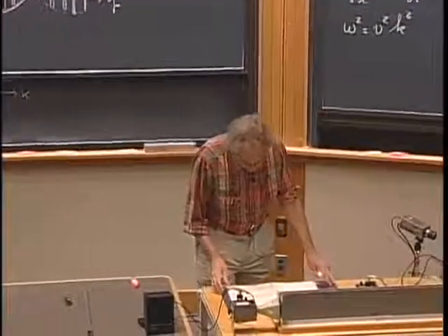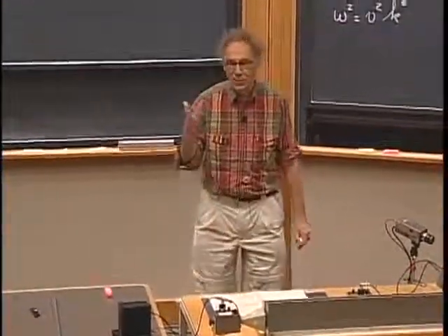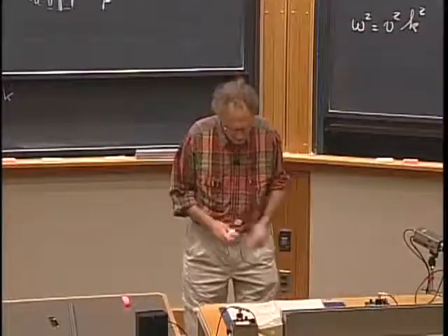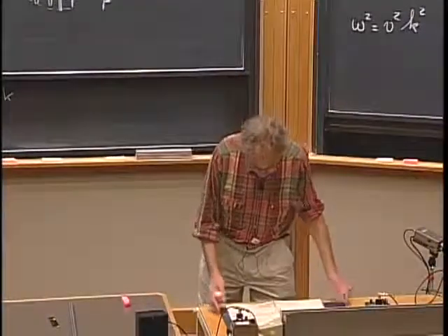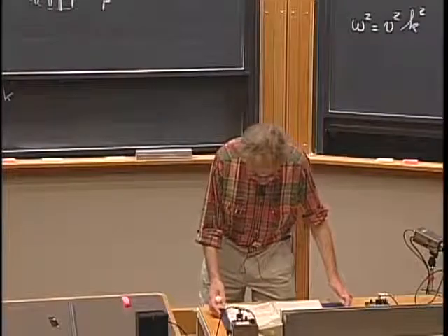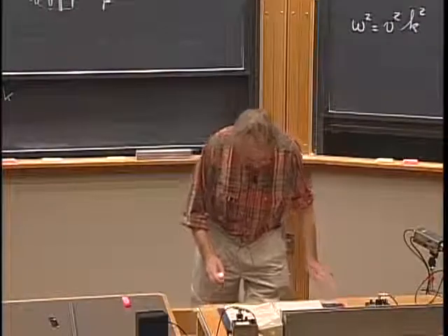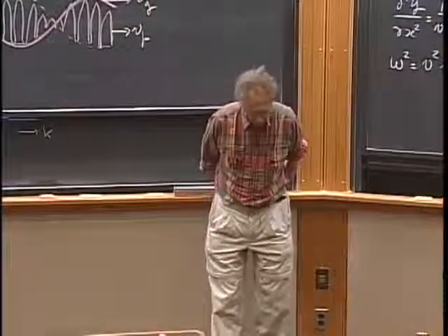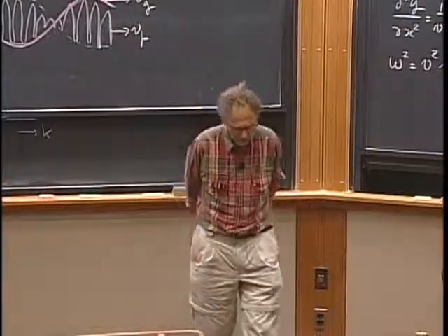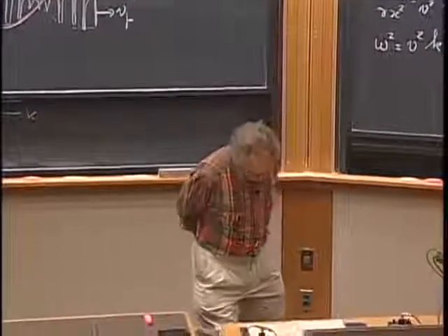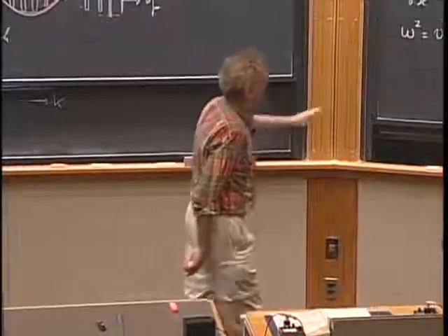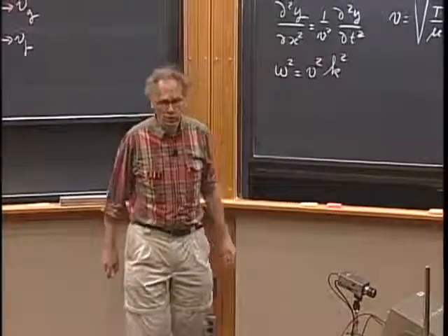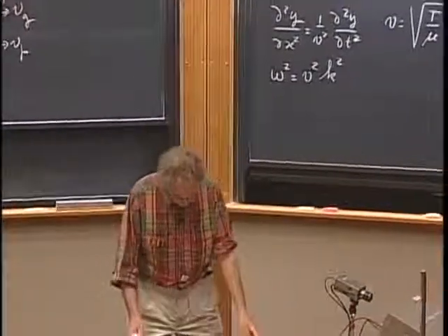And it is due to the stiffness that you get an extra restoring force, which we have ignored. We didn't take that into account. And the restoring force due to stiffness turns out to be proportional to k to the power 4. It's inversely proportional to the wavelength to the power 4. It's an approximation. In other words, our wave equation is no longer valid, because this wave equation only took into account the tension.